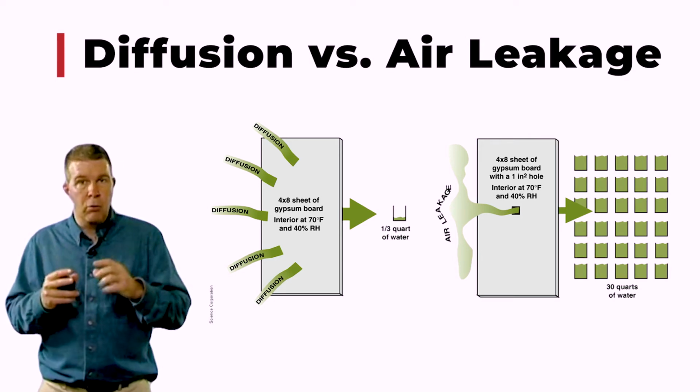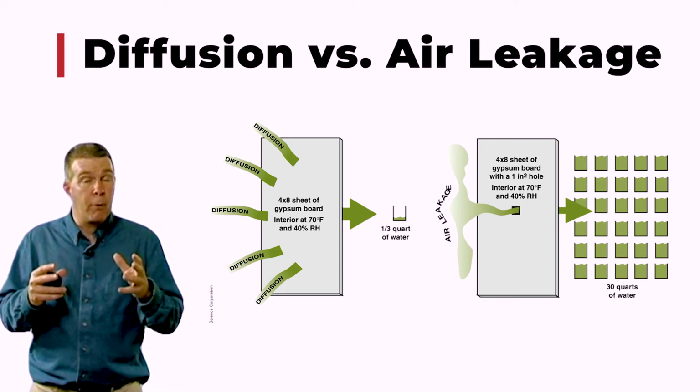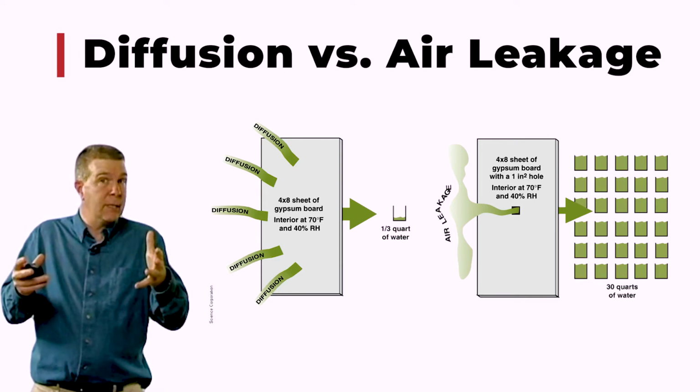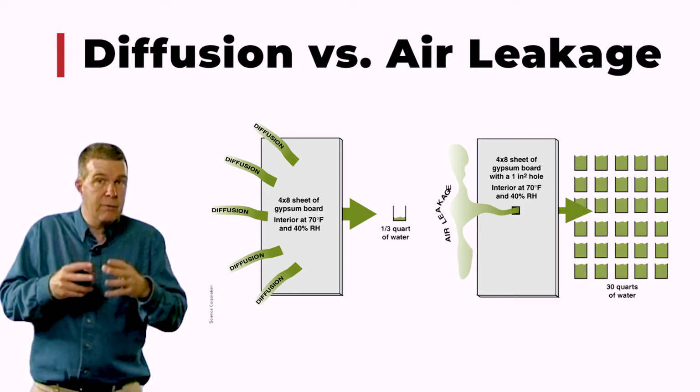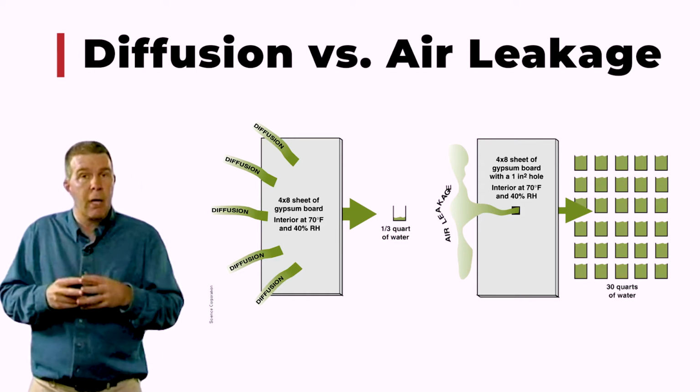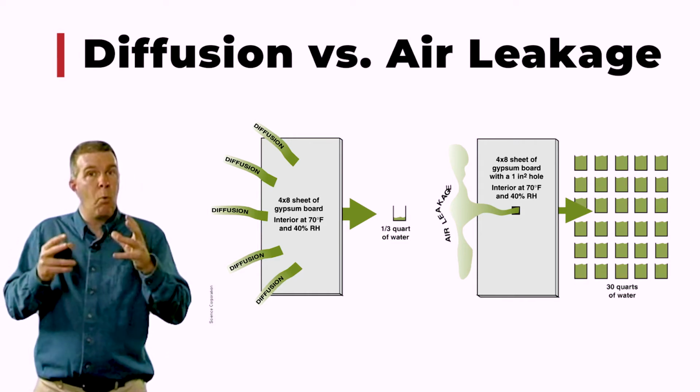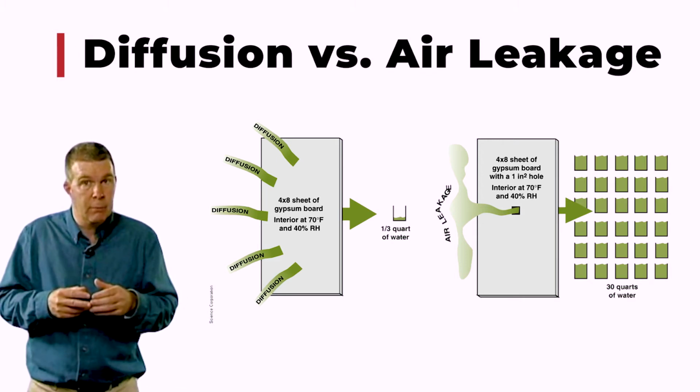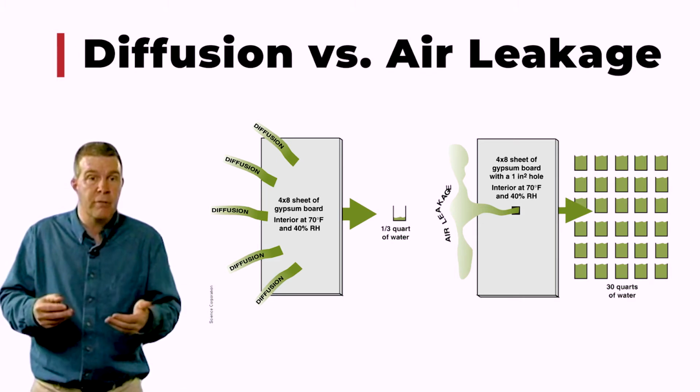If you've got a hole in your system and you haven't sealed properly, or somebody like a tradesman hasn't done something that they're supposed to and leaves a 1 square inch hole in your system, it's that amount of water that can come into the house. And it's that water that's going to bite you when it comes to the proper performance of the entire system.